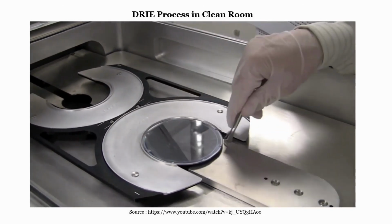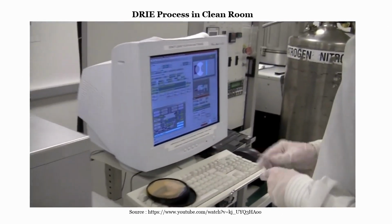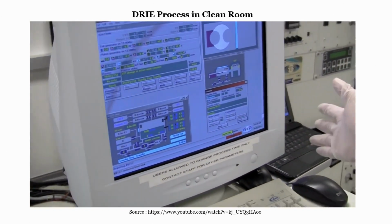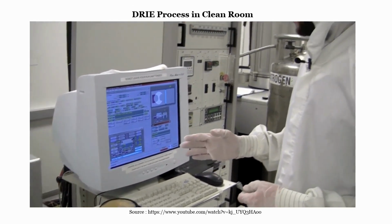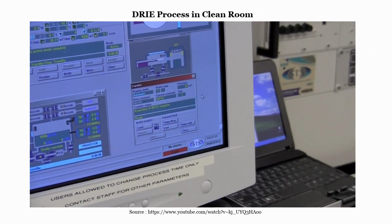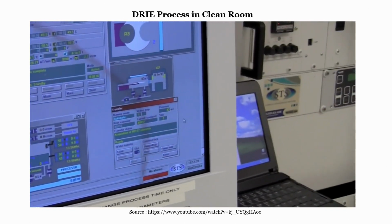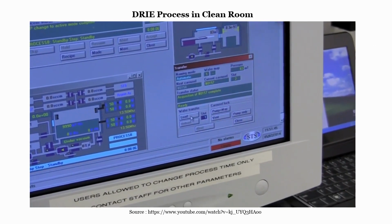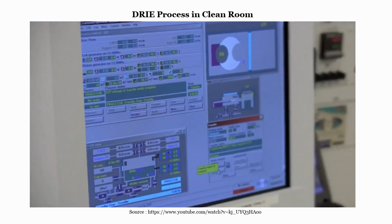Once we have the wafer properly loaded, we close the load lock chamber, and we go to the transfer window and press pump and map. Now the load lock chamber is going to be put under running conditions, and it's going to also scan to see where the wafers are placed. Once the software has mapped the slots in the carousel, we will load the desired one. In our case, we have our wafer in slot number 1. We just have to press load, and now the machine is proceeding to load the wafer into the chamber.